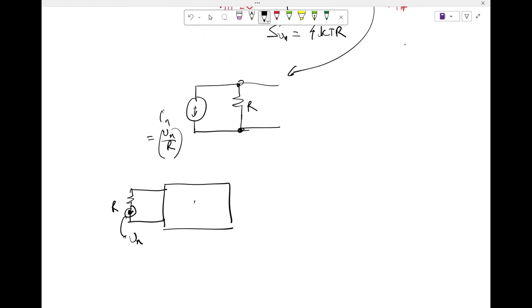And let's say this has a gain of A. I'm coming back to wherever we started. So clearly, the voltage that I'm going to observe here, assuming Rin is infinite, let's say, no loading. So the voltage that I'm observing across this terminal is also Vn, correct? So the output that I'm going to get is Vn times A, correct?